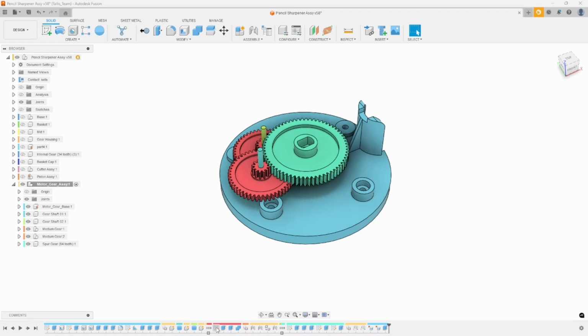As I continue stepping along, now we're taking a look at this red part, and this is where I created this gear. So obviously I started with a sketch, did an extrude, combined the small gear with the larger gear together, etc. Then I obviously did the larger gear. Sorry, I skipped over. There's some revolute joints.